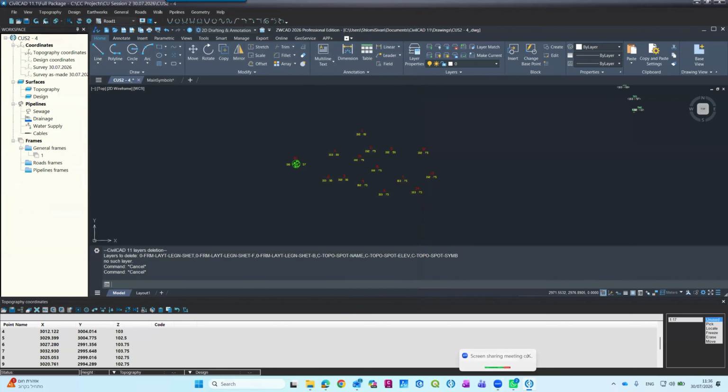Okay, let me answer some questions. Can coordinates be uploaded from handheld GPS and RTK, or should we manually input them? Of course, you can upload them. If you have an RTK or even handheld, you just download the list into a TXT file, which usually it comes with every RTK today, and open here and upload it.